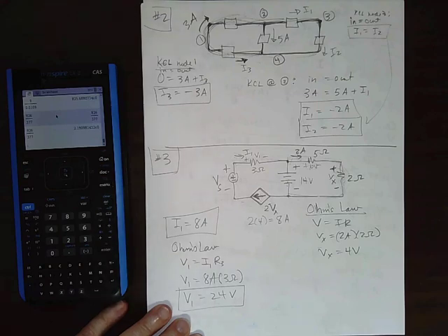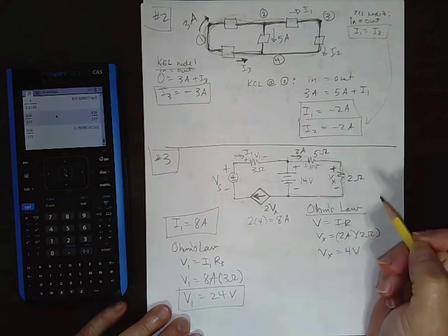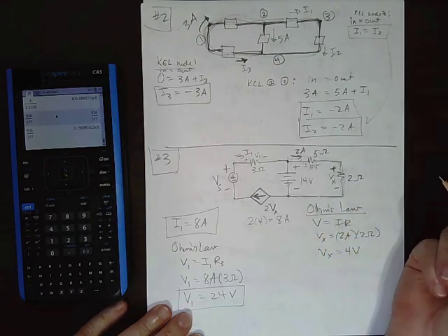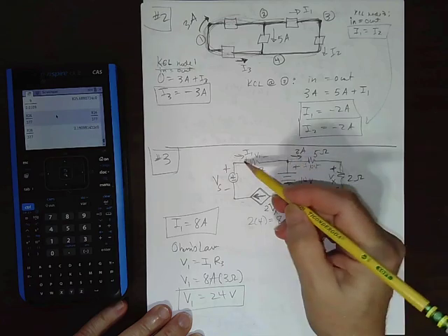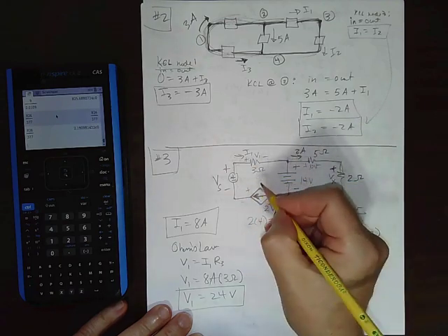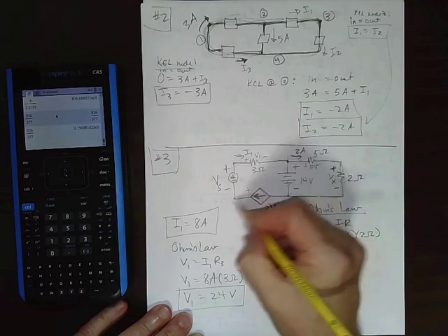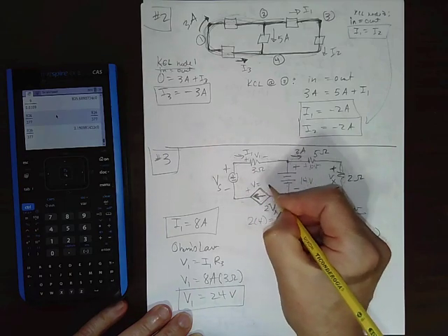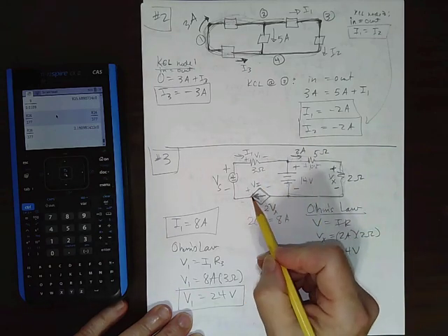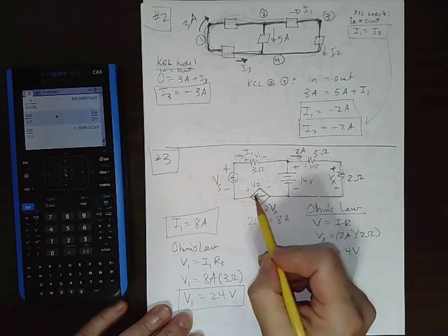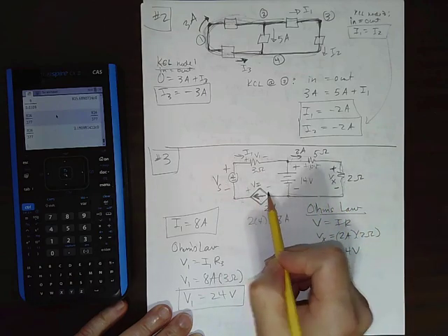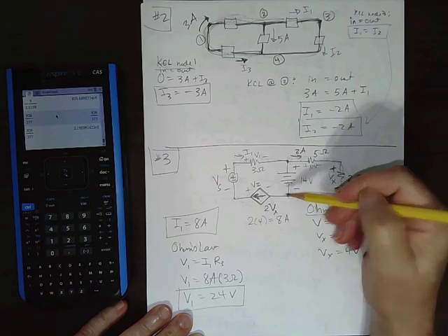Yeah, I don't think we can get Vs from this information, or from the way I have this circuit put together. Why not? Well, we know the voltage here, we know the voltage here. So we could try to name the voltage. Usually with sources we have positive coming out, so we call this VI, maybe for the current source. So put this, it's positive voltage where the current comes out. All right, so we don't know Vs, we don't know Vi. We know this voltage across here, so let's just try.